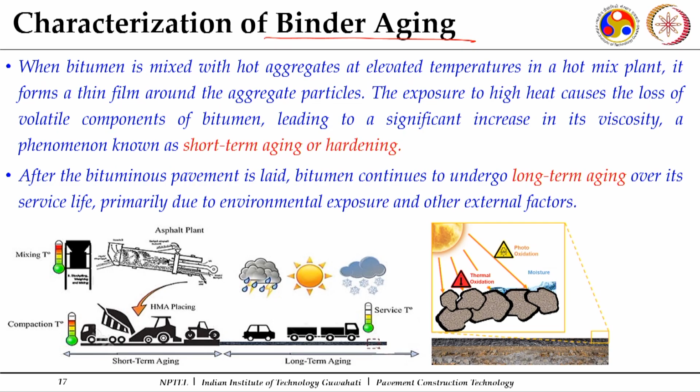So, the viscosity of the binder increases. Now, if this aging is very high, it makes the binder unsuitable at a later stage of service life. So, some good characteristics of the binders are lost. That is why we want to ensure how much aging takes place, how susceptible a binder is towards